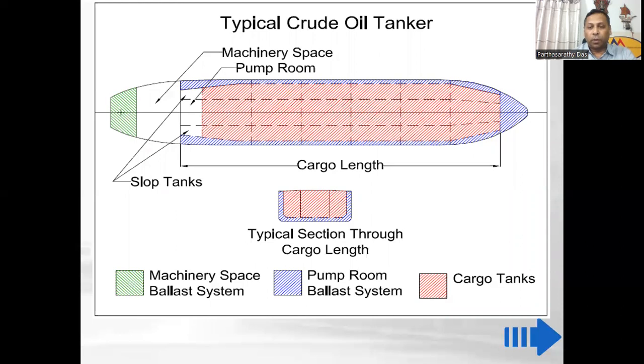Next, on this particular slide, we can get a general idea of how a ship's ballast system is. We can see in the light reddish areas on the photograph the ship's cargo tank spaces, and surrounding them in light blue, we can see the ballast areas of the vessel. These are basically different tanks, having sections with these lines that we have been identifying in the photograph. And on the aft, we have the ship's engine room areas and the ballast in the engine room as well.